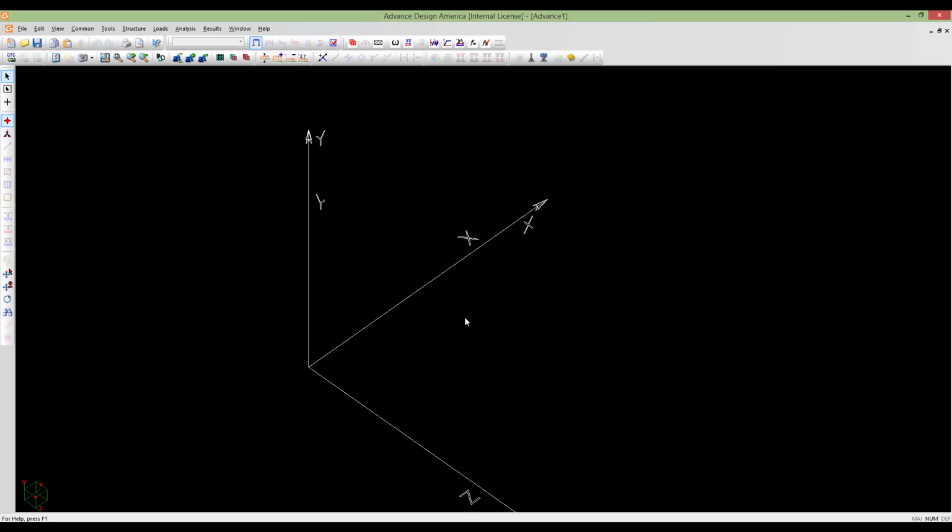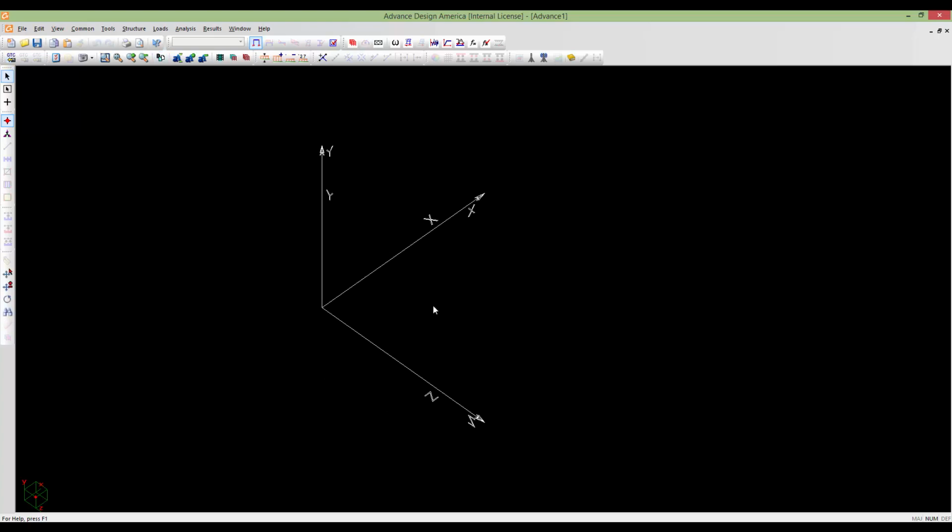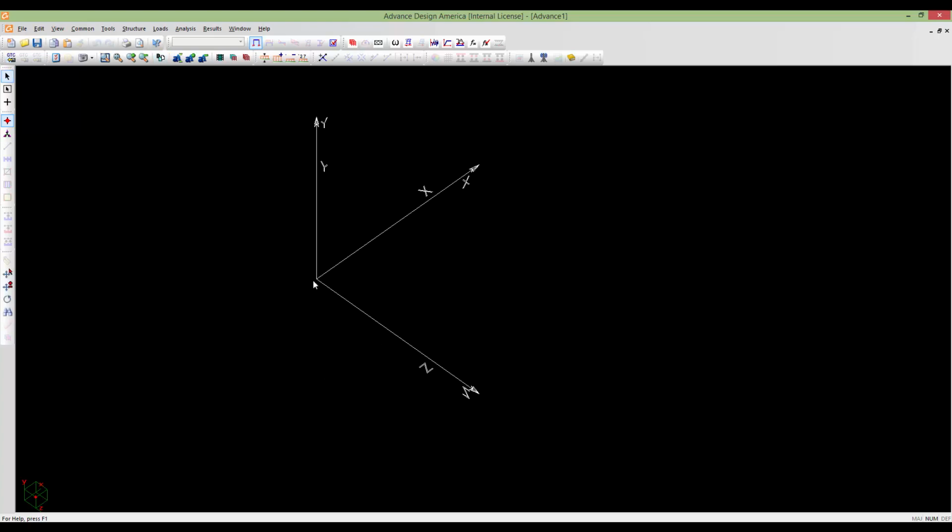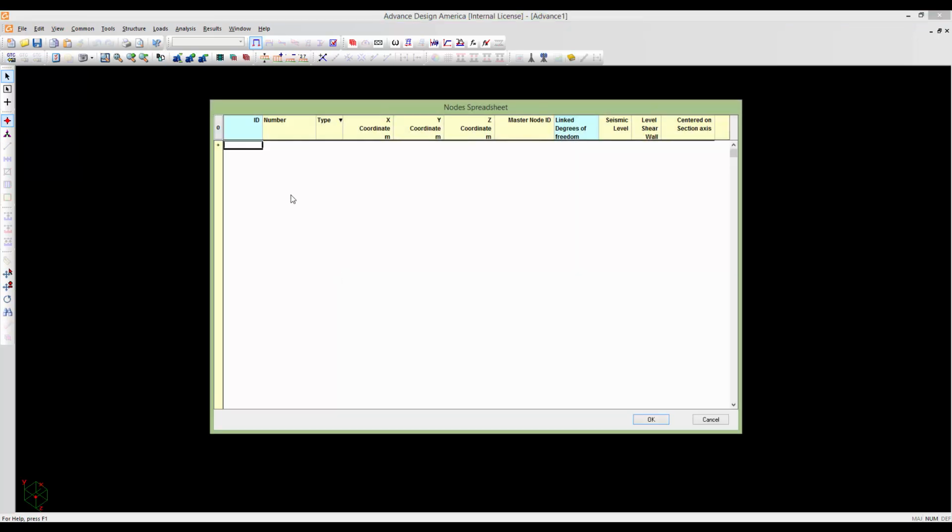In the next step, I will model the project. So firstly, we will model the first beam here, and afterwards we can generate the beam to have the full complete 3D bridge. And the bridge will have 4 box girders to cover this span. So I am in the node mode, Control H. I will add 2 nodes. For the first girder, it's starting from 0 coordinates, and I'm going to define this length of 42 meters in the Z direction.